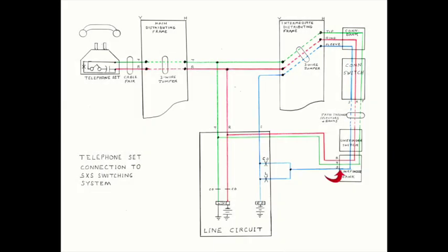As we can see from this diagram, there is battery on the calling line sleeve terminal that originates on the far side of the line circuit's CO relay winding, through the operated make contacts of the line relay and to the sleeve bank terminal. The connection of this battery through the sleeve wiper into the line finder switch closes the operating path for both the CO relay in the line circuit and the F relay in the line finder.